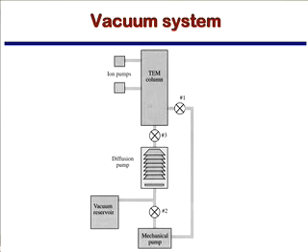You will pump on the back side of this diffusion pump so that if there are things coming out as this thing warms up, you have a way to take them out so they don't just jam up in the diffusion pump region. You'll also pump on what's usually called the reserve tank or vacuum reservoir, which is just a big empty volume that you pump out so that if there are hiccups or problems along the way, there's a place for extra gases to go.